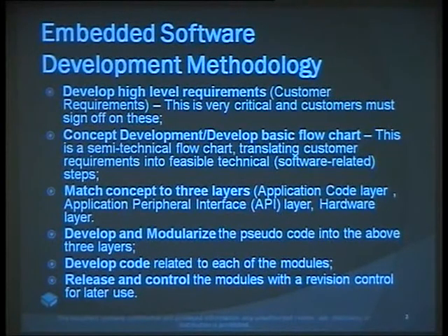In one PWM cycle, you have various priority tasks, and if you continue to evolve or add more requirements, you can even add higher priority tasks. Let's say you have to respond to the keyboard. The keyboard will not come in an interrupt; it will go on in an infinite loop program. Then the PWM interrupt, whenever the requirement comes, interrupts this program and does the PWM configuration. That's the highest priority.